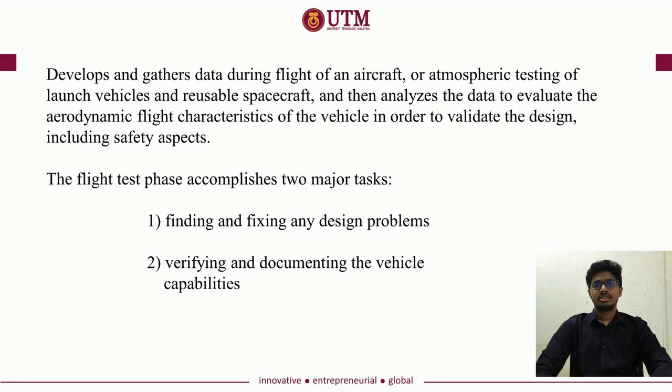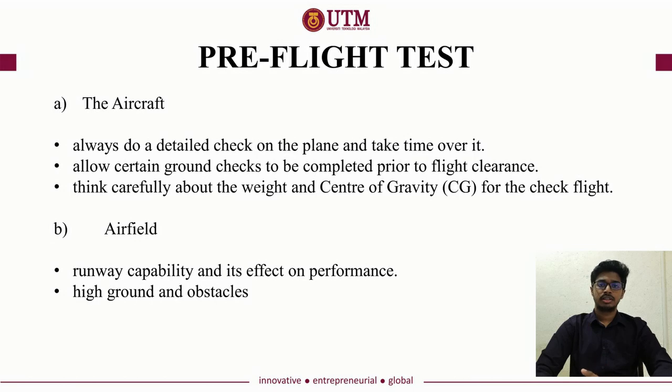So flight tests consist of two major phases. The first would be finding and fixing any design problems, and the second would be verifying and documenting the vehicle capabilities. The flight test phase can range from the test of a single new system of an existing vehicle to the complete development and certification of a new aircraft. So there are four parts in flight testing.